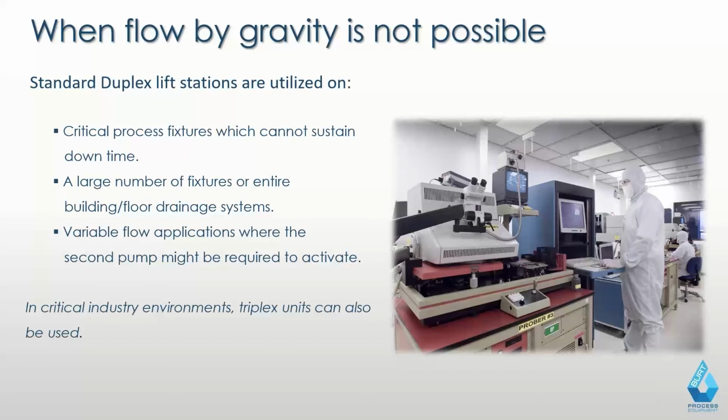It's also the reason why lift stations do not apply diversity. So when you're talking about gravity flow to a system very often, you're talking about 20% diversity or 30% diversity. But when talking about a lift station or pump-based system, you're always talking about applying no diversity because you have to be able to always pump down your system. And typically you take whatever the maximum flow rate is to it plus 10% to allow you to always do pump down in those cases.